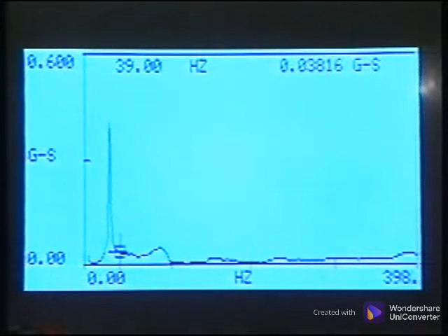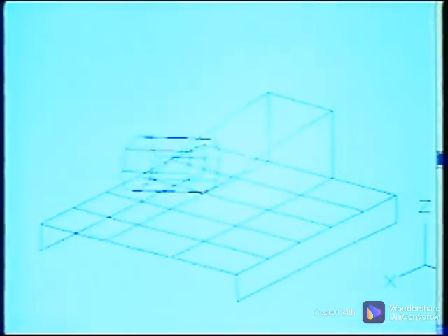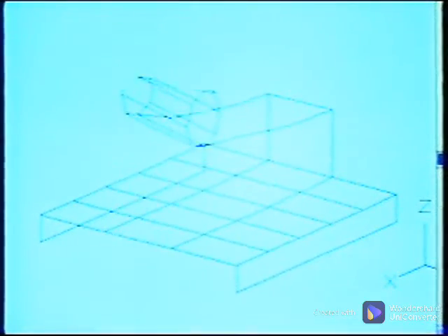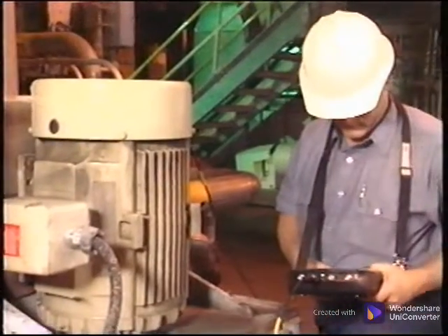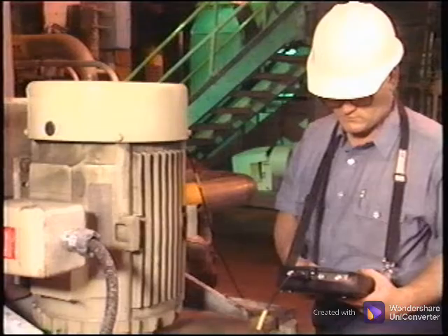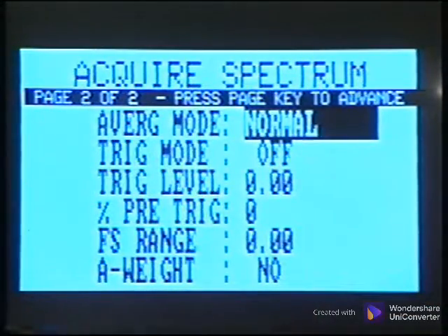In this program, we examined in detail the characteristics of resonance and many single-channel analysis methods for resonance detection, as well as introducing the benefits of multi-channel analysis techniques. Our interview guest, Mr. Art Crawford, pointed out that resonance could be the number one machinery problem in industry today. Resonance can elude the analyst, so perform several tests to confirm its presence and determine the source of the forcing function. When using normal averaging for a bump test, the machine must be off.